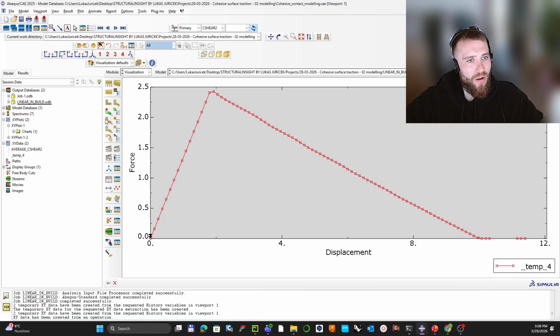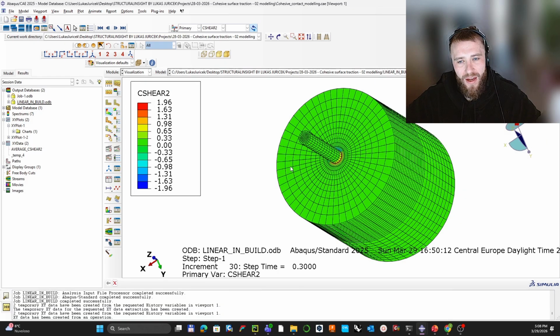And right now we will just double check what is happening if you put the user-defined damage and the slip into the ABAQUS. I just outlined the very brief results because in the next session we will go deeper into explanation of the results, how it works, and how the criterion has been built up and many more. But at this phase, I will just come back to Python and introduce how the damage is calculated.